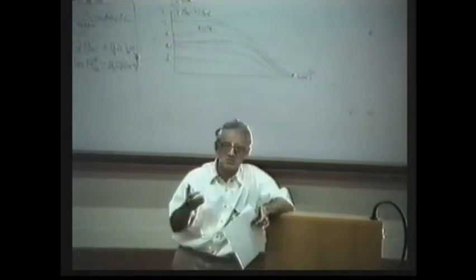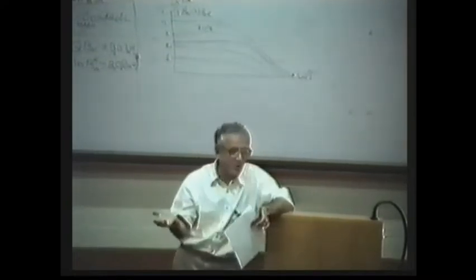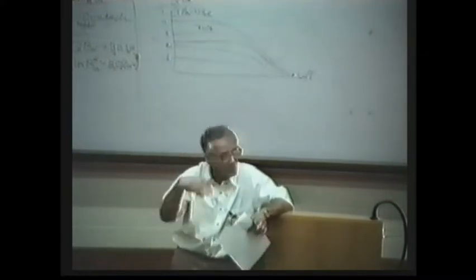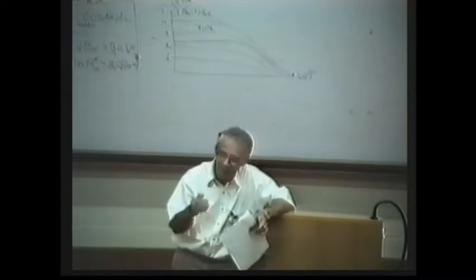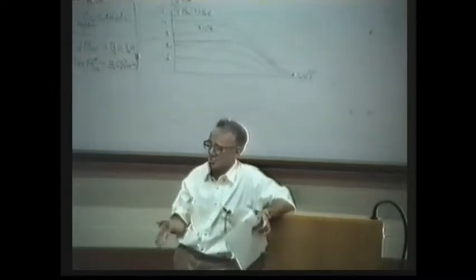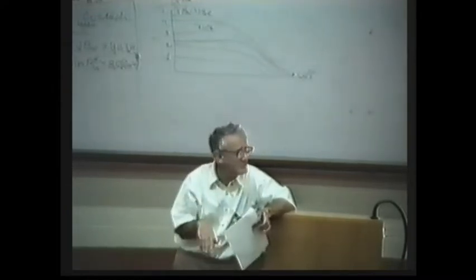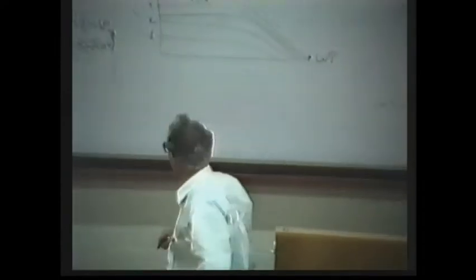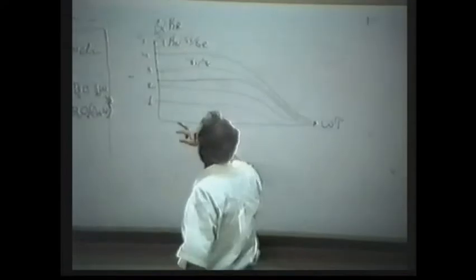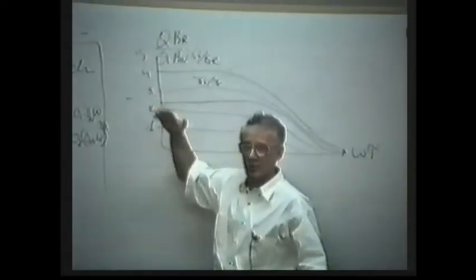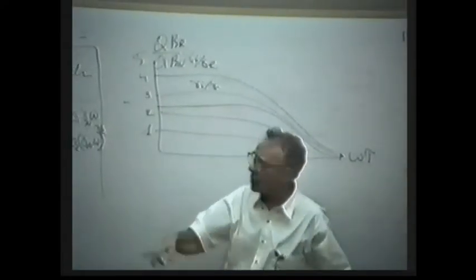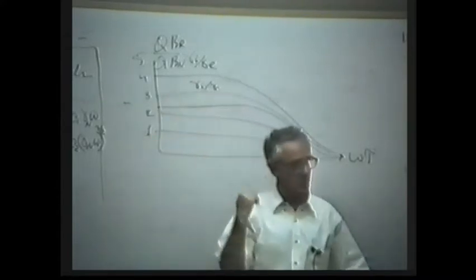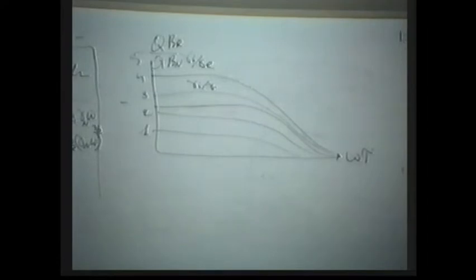Then take very known programs for a horizontal layer medium, for overburden or host rock, or for both. Calculate, that would be my noise. Then take the ratio, and if at the low frequency part of the spectrum you see the ratio for given depths would be greater than 1, there is a good chance we will detect.